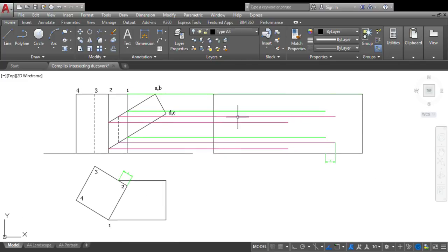length of 4 divisions. So if we install our bend lines here, so this is essentially giving us our development of the part and plan. Or sorry, the development of this square base box section.